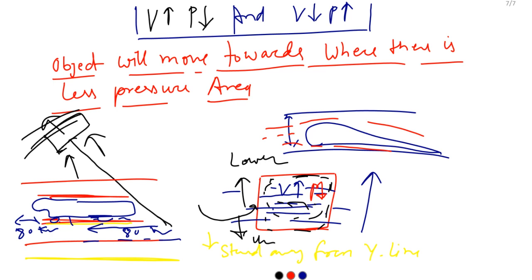So this one is a platform, this one is the yellow line, and if you are standing here somewhere, what will happen? There is a certain pressure, and when the air is moving so fast between you and the train, because of higher velocity, the pressure at this particular point will decrease and the air will try to suck you inside. So there may be chances of an accident. The announcement is going on because this yellow line is a calculated distance at the maximum velocity of the metro train.